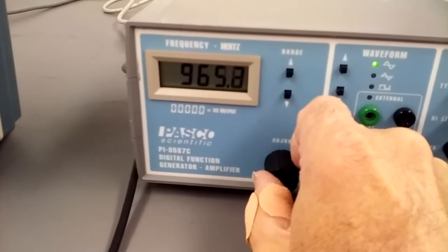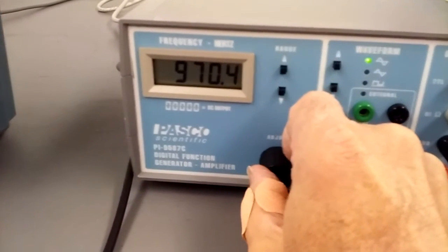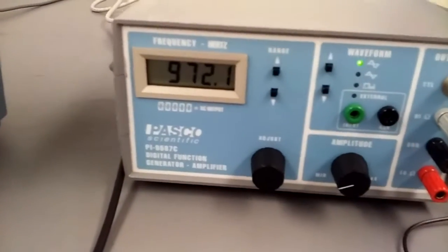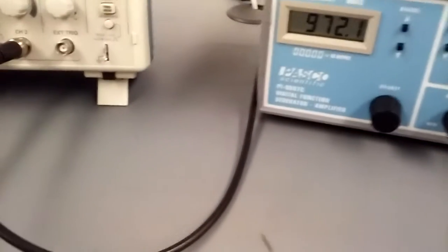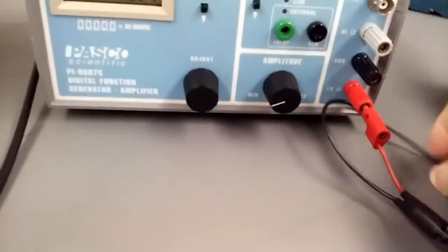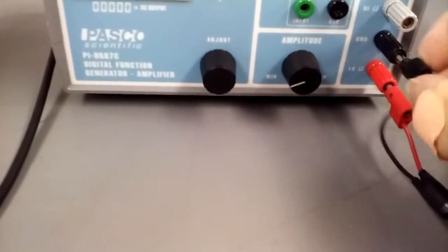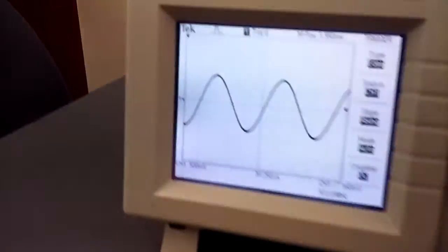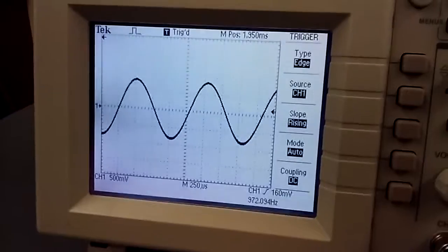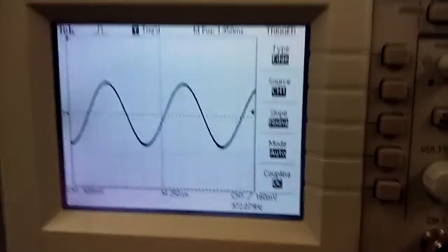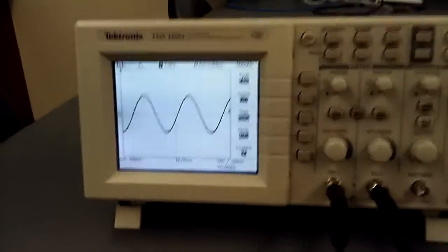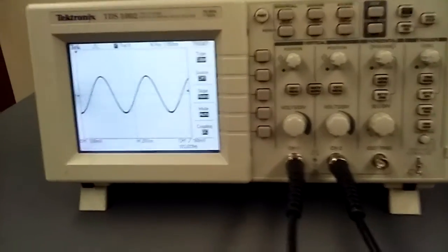So anyway, okay. Let's say I take my cable that's coming from my scope and I connect it to the function generator, all right? So let's connect it. Now what I'll see on the screen is a sine wave. That's plotting the voltage that's coming out of the function generator.